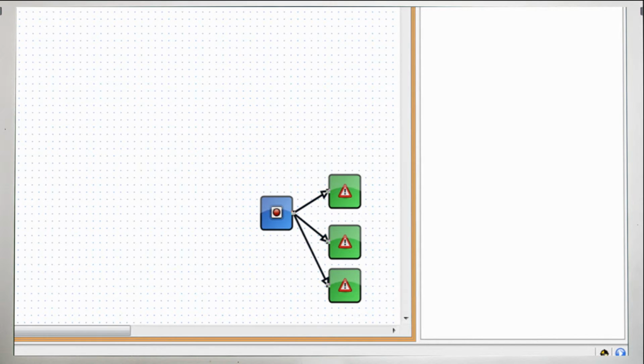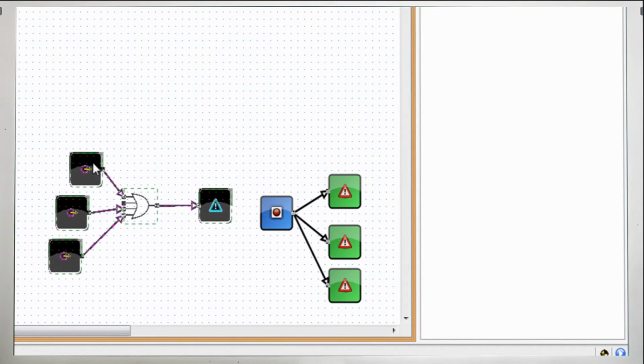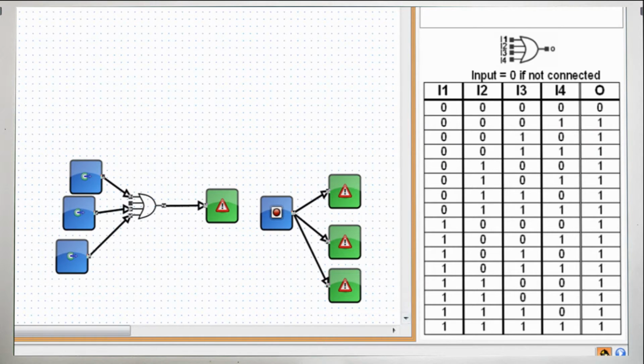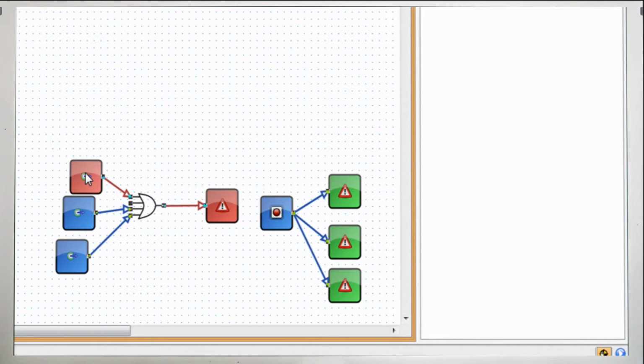However, you cannot connect multiple logic outputs to drive a single input. For the script to function correctly, the multiple outputs must be grouped through a logic gate, typically an OR gate. This allows any one of the three objects to trigger the alarm.